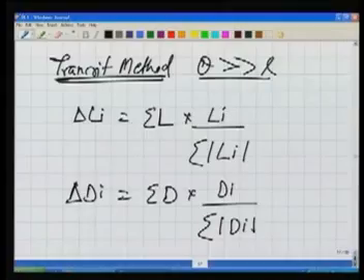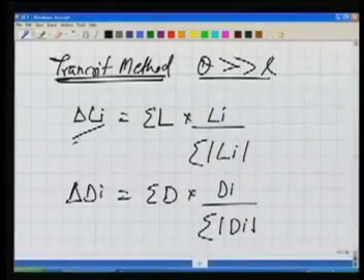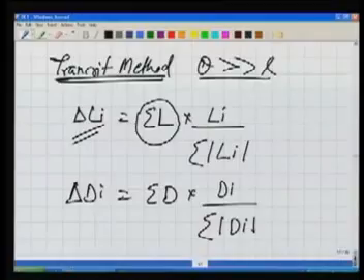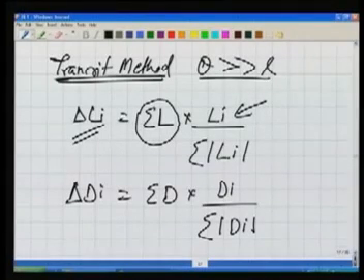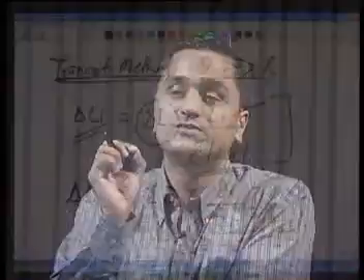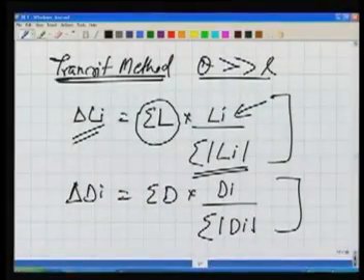So what we are doing here, we are distributing the corrections for individual lines. The correction means the total error in the latitude is sigma L. We want to distribute it. So we are distributing here in proportion to the latitude of the line, and for that we are not taking the algebraic sum here, we are just taking the numerical sum. So this is how also we can apply the correction to our computed latitude and departures.